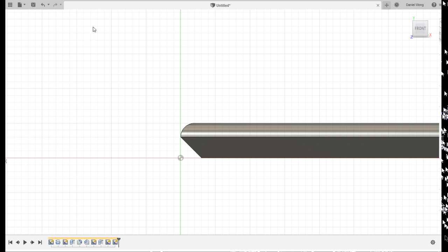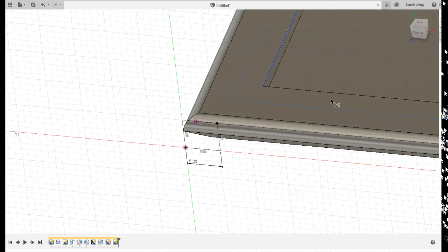So I'm going to find a position that I want to make using a rectangle, and I'm going to make sure it's construction because I don't want it to be physical geometry. I can select the origin, and I can map out exactly where that is to be 9 minus 3.75. Like so. 9 is the distance to this line here, and then minus 3.7 from the very tip.